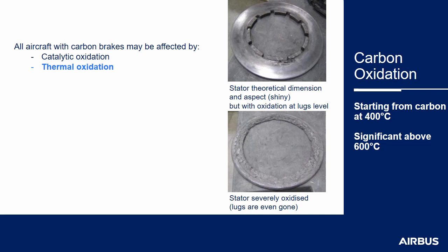Indeed, thermal oxidation is a natural oxidation process that is due to the porous texture of carbon when the brake is exposed to high temperatures. This phenomenon starts at temperatures as low as 400 degrees Celsius and becomes significant above 600 degrees Celsius.